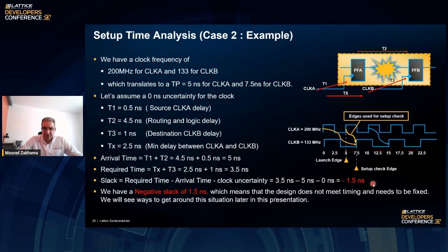This is not good, meaning that we have a timing violation. And this is where knowledge of the design comes in, making sure that you understand what's going on. If this situation is covered by design, you need to tell the STA tool to ignore these paths so it doesn't analyze them and doesn't try to optimize them to hit the 400 megahertz clock or the 2.5 nanosecond requirement for that setup time analysis.